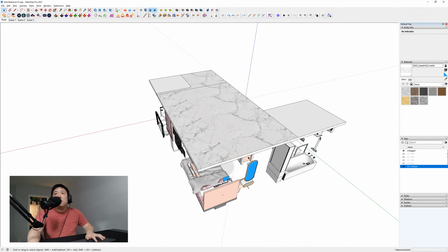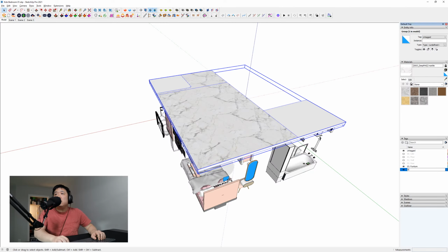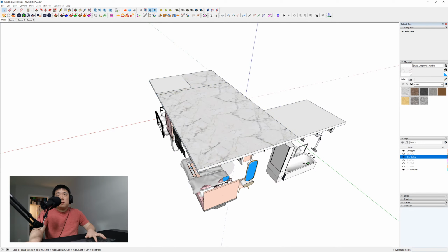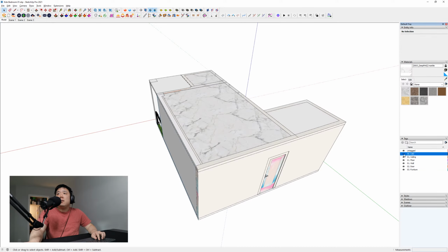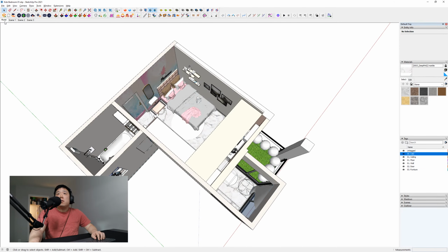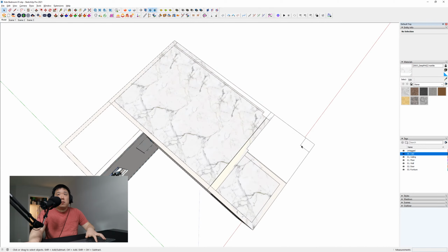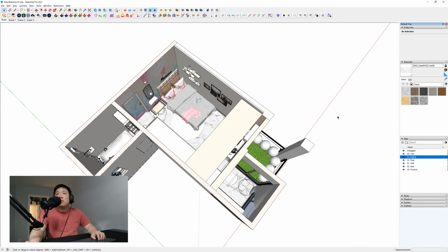And if I unhide all, there is a ceiling. So let's do the ceiling again. Ceiling tag. And then that goes to ceiling layer. So at least theoretically, everything in this model exists inside of one of these tags. So if I go to the model layer, unhide all, and then just control everything by the layer. So update that. So that's how I would do that.